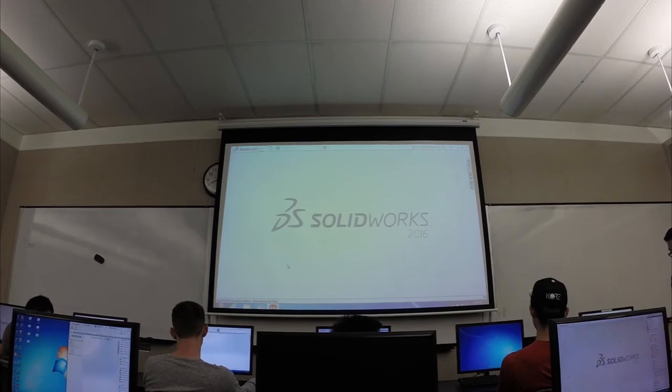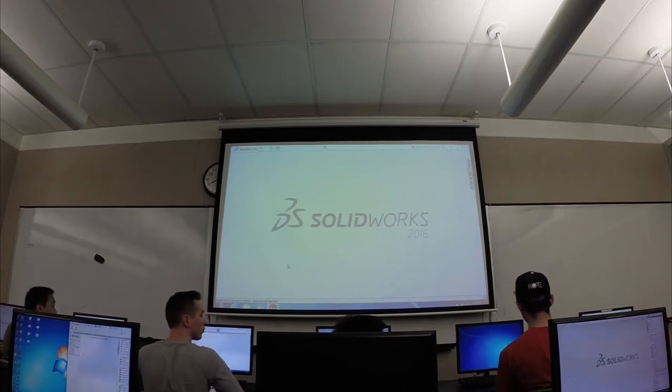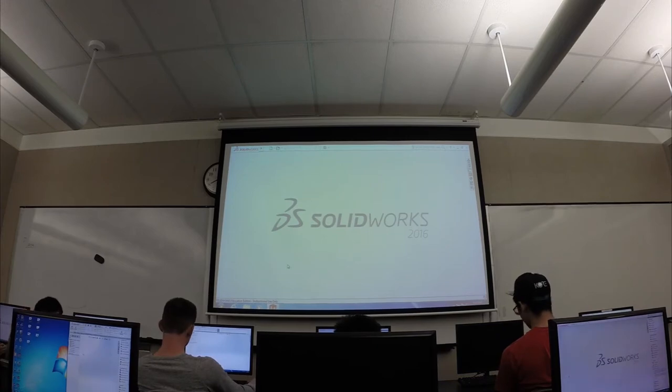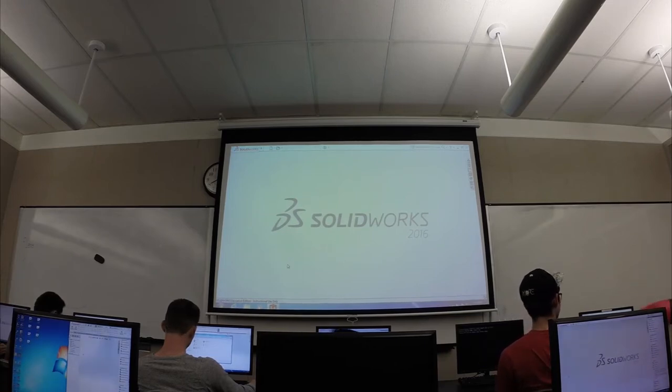The next part about some design principles with CAD is editability. What that pretty much means is, since it's parametric modeling software, you can change certain things that you made. So if you have this part like this, right? You can roll back in time and say, okay, I want to change this circle into a square, right? So from here, you could immediately switch into a square extrusion. And things like that really depend on how you go through your steps. If you make your steps really complex and undefined, you're going to find it really hard to make certain edits.